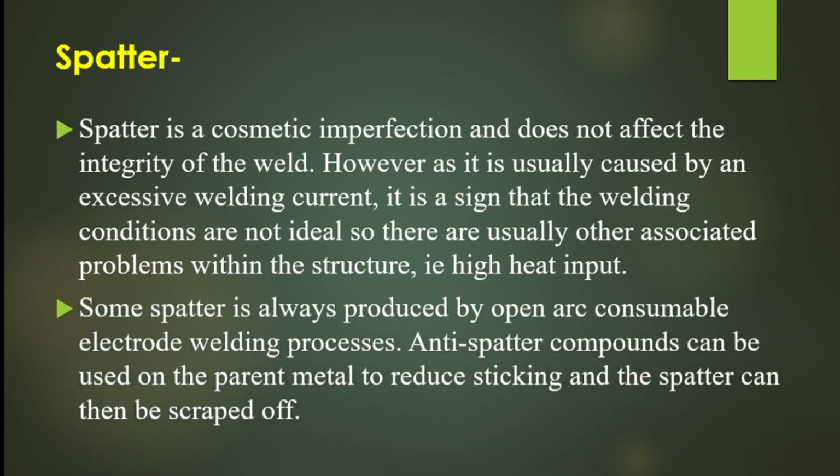Then second thing is some spatter is always produced by open or consumable electrode welding processes. Anti-spatter compound can be used on the parent metal to reduce sticking, and the spatter can then be scrubbed off.